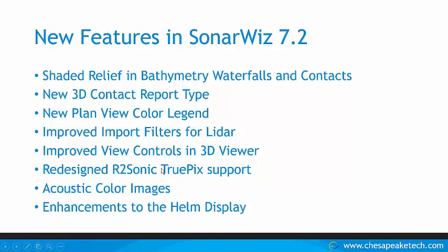Also related to R2Sonic, we're starting to see multi-frequency systems more often. We've had them for side scan for a while, but now we're getting multi-beam systems, starting with R2Sonic, that can actually change frequency on each ping. It gives you an opportunity to look at the seabed at different frequencies and how the seabed responds. One of the tools for analyzing this data is acoustic color, and I'll show you exactly how that works in a minute.